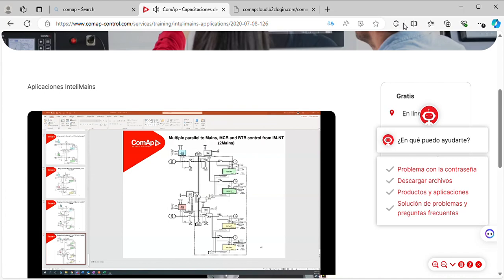So it is feeding up the load now. So they are load sharing between them. You'll see the kilowatt is going down. But my load is unbalanced, so there is a trip signal. I just go and press a fault reset, reduce my load on the simulator, and you will see the system will restart again, and it will synchronize again to the system and take care of the load.